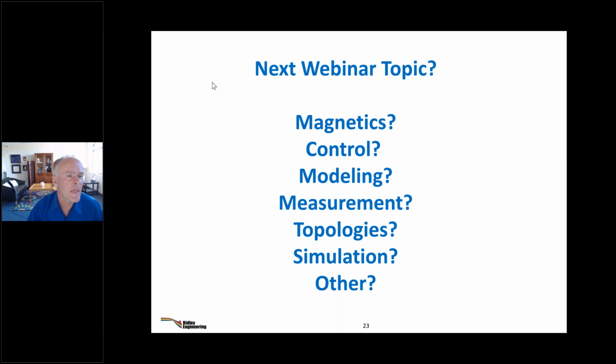Flyback, input current. Yeah, input current is the right place to sense the current for the LLC. Yes, it is. You want to do it on the low current side in general, so it goes in series with the transformer. But look this up on some of the app notes. They got some really, really clever sensing mechanisms for looking at the input current.